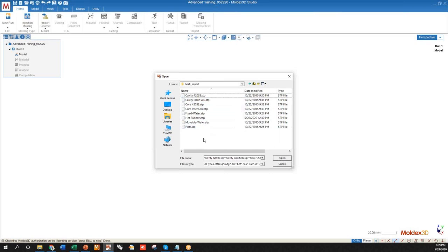As long as the heat transfer properties are the same between all these components, then they could really just be considered one block of material. So if anybody's run Moldex3D through our trainings, we just recommend you put a mold base, which is just a box, around your system. And that box is where all of the heat transfer is going to occur. Like I was mentioning, any component that's the same material can really be assumed to have the same heat transfer properties, and therefore we don't really need to model in those components directly.